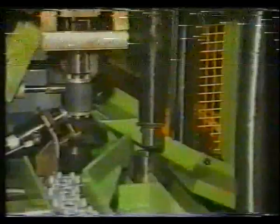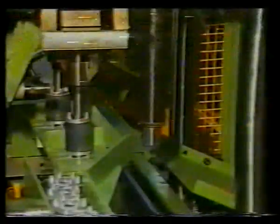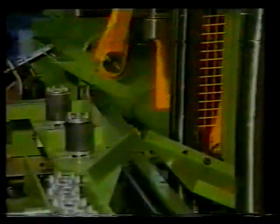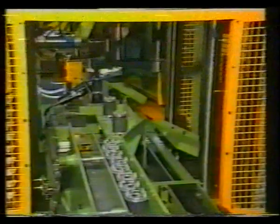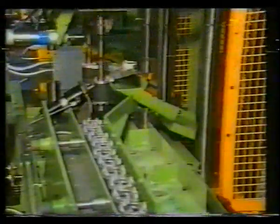After opening the press up to the intermediate stop, the sliding table moves to the pick and place loading position, and the rotors are pushed onto a horizontal plate. When the sliding table returns, the rotors are pushed into a separate channel by means of a deflection plate, from where they're taken for further processing.